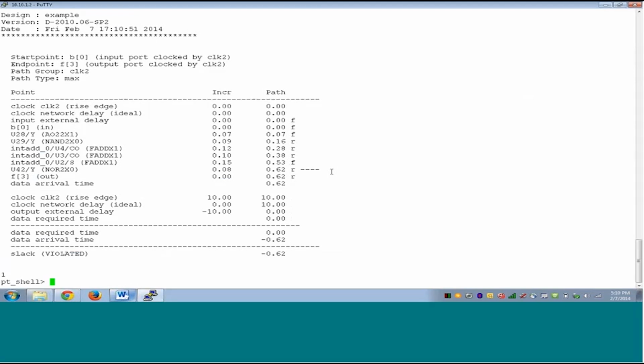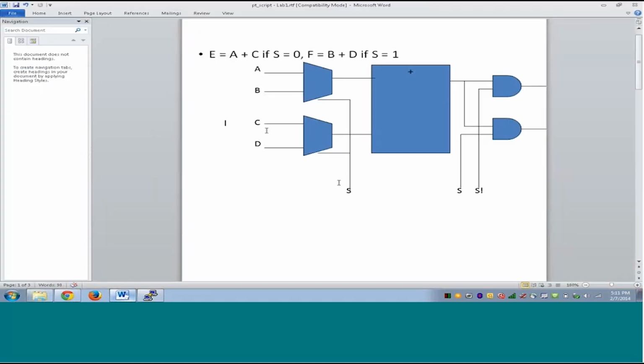So earlier we had to give false paths for each set of inputs to each set of corresponding outputs. We had to give 4 set false path commands, and let's say if you want to expand your design, you have multiple cases like this, then you need to add so many other false paths, right? But in case of virtual clocks, we just give 2 false paths from one clock domain to the other clock domain, and this can easily scale up. Let's say you add more inputs here. The number of inputs you add, number of similar functionality you add, you can again segregate into virtual clock domains.